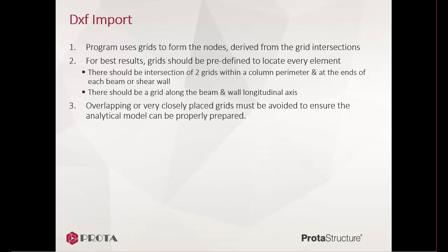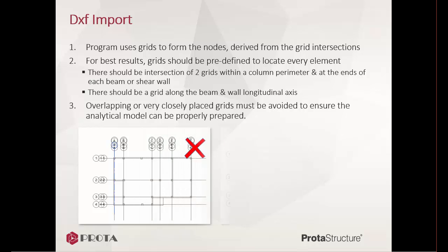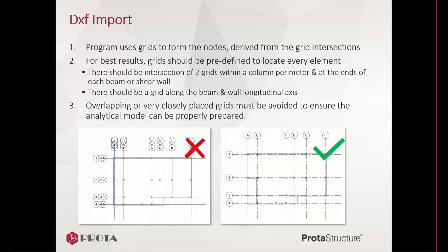Overlapping or very closely placed grids must be avoided, to ensure the analytical model can be properly prepared. In this example, the left picture shows a messy grid system, which should be avoided. The right picture shows a clean grid system, as recommended above.